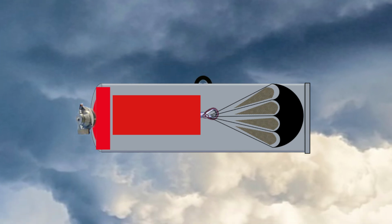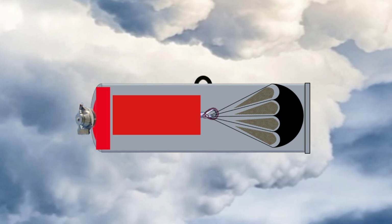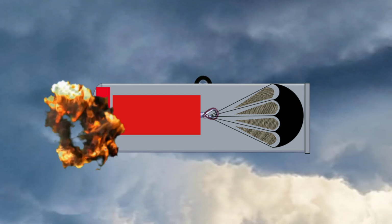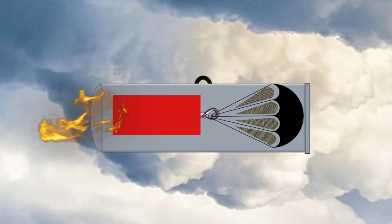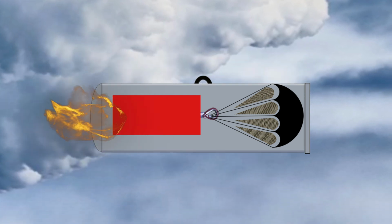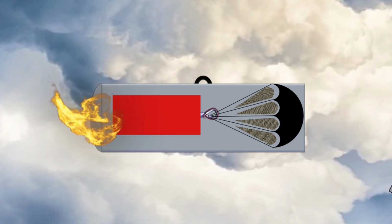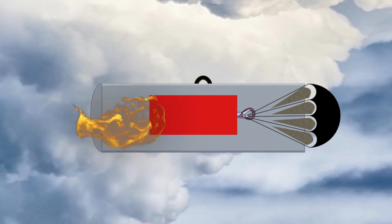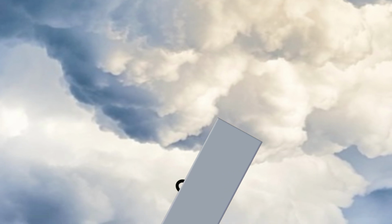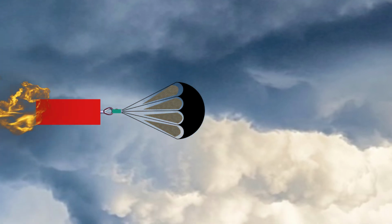After release from the aircraft, the target flare will have a free fall for some time. After the expiry of the preset delay, the fuse will function. It will ignite the explosive pad. The explosive pad has two purposes. First, it will initiate the flare composition, and the gas pressure produced by it will push the flare along with the parachute towards the rear, and the rear lid will break open. The candle along with the parachute will come out from the container. The container will fall separately. The parachute will deploy and the candle will keep burning.